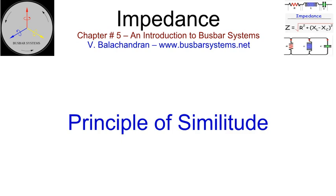The skin effect and the proximity effect will remain the same for a constant ratio of root of frequency by resistance. It is necessary to test the setup at 4 times the frequency. If the area is reduced by half, it is necessary to test the setup at 2 times the frequency. The resistance drop will be 4 times than at the rated current. Since the inductance remains the same, the reactance drop will be 4 times than at rated current. The resistive and inductive drops retain the same proportion. The scaling down can be generalized to any index n.